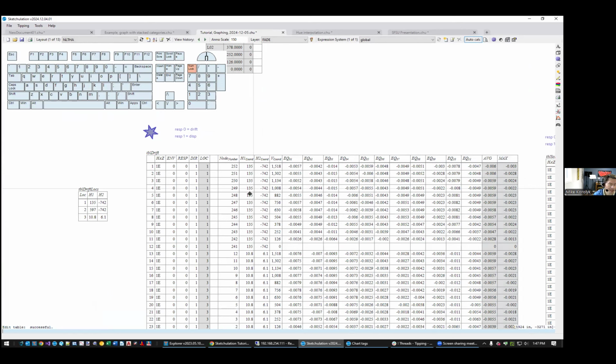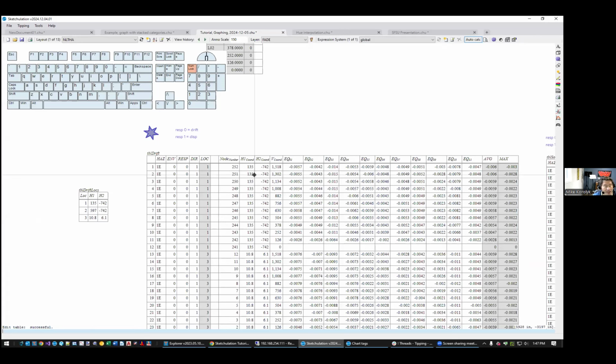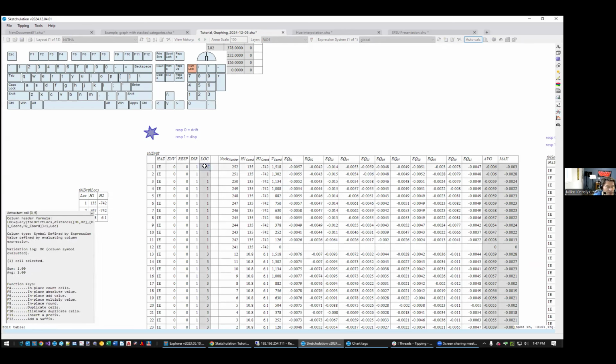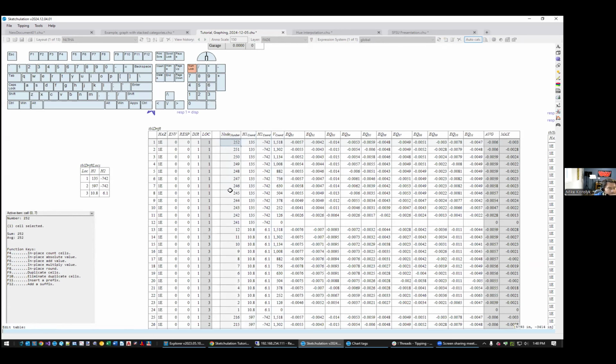And when we exported this data from Perform, the program that we use for the time history analysis, we exported both interstory drift ratios and deflections. And we also exported data from multiple locations within the floor plan of the building. These three columns here represent the coordinates of those points. So we have the vertical coordinate, so I can see where they are vertically, and then the H1 and H2 would be the X and Y, horizontal coordinates for these, and then we have a node number.